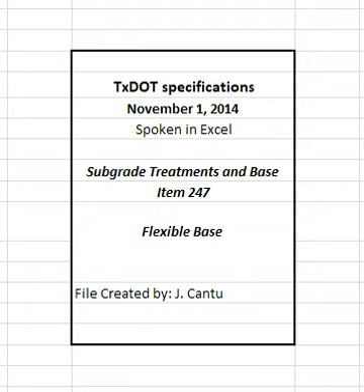The engineer may accept material if no more than one of the 5 most recent plasticity index tests is outside the specified limit. No single failing test may exceed the allowable limit by more than 2 points.